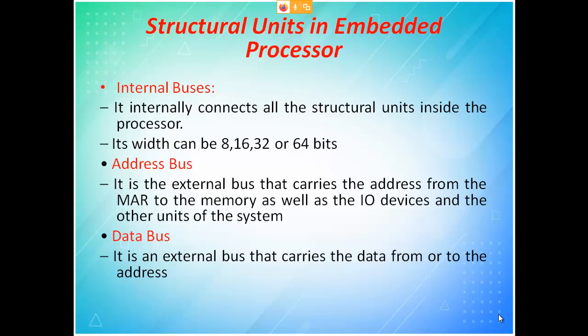Okay, if we assume you have one address line, then you can address 2 memory locations, which means if I put 0, it is the first location of my memory. If it is 1, it is the second location of memory. So 2 to the power 1 is nothing but 2. So if you have one address line, I can address a memory of 2 locations, which means 2 is the number of addresses of the memory, not the capacity of the memory, that you have to remember.